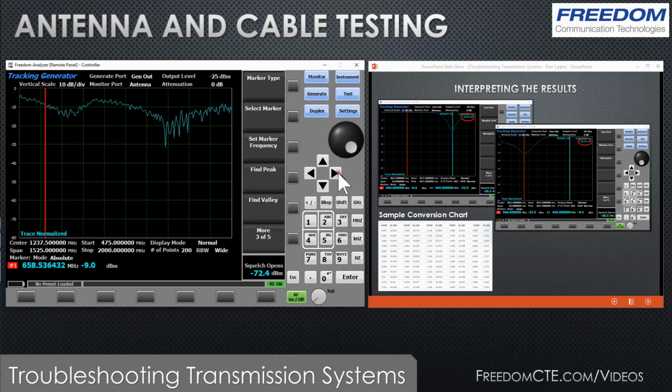so that's not too bad. So really, when I'm looking down at the bottom here, I'm looking at negative 14, and if I add 6 to that, I'm really looking at a return loss of 8 dB.